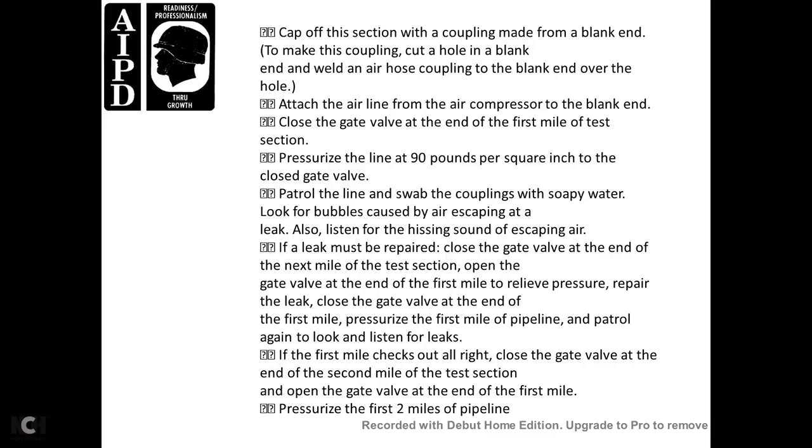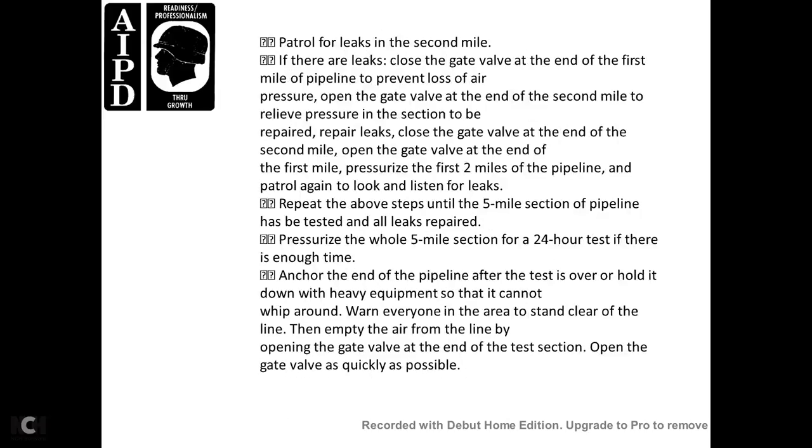If the first mile checks out all right, close the gate valve at the end of the second mile of the test section. Open the gate valve at the end of the first mile. Pressurize the first 2 miles of pipeline. Patrol for leaks in the second mile.